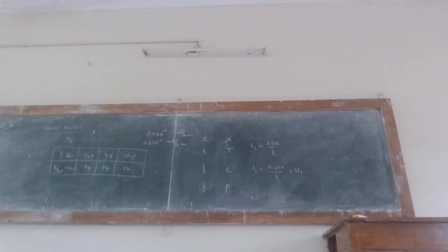Okay, fine. How much order did you get? Second order. Good. So the next question. Liquid A decomposes by first order kinetics in a batch reactor. 50% of A is converted in 5 minutes. How long will it take to reach 75% conversion?